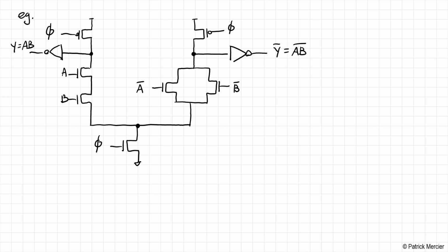Now we do still have this issue of charge sharing, okay? And so normally we had to go through the inverter to get the charge sharing mechanism sorted out. In this case, with our dual rail domino circuit, we can do something slightly more clever, and that is to build a cross-coupled PMOS pair.